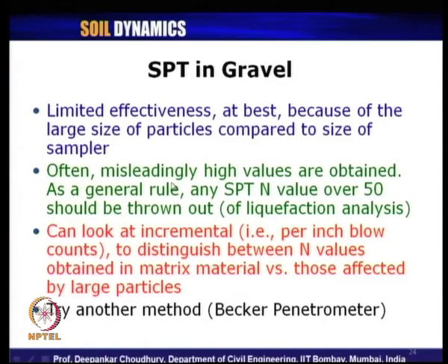So, often misleading high values are obtained, and what is the general rule? If the recorded SPT N value is more than 50, then most of the time we need not carry out the liquefaction analysis, because we assume that the soil is not going to liquefy if the SPT N value recorded is more than 50 for a plenty of repetitive tests.